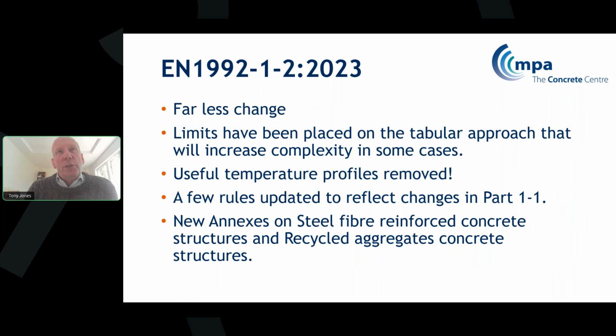There's also been a few rules updated to reflect changes in Part 1.1. So there's also rules for steel fibers in fire and steel fibers and recycled aggregates in fire. It's worth looking at this if you're considering using recycled aggregates, because it is quite restrictive.